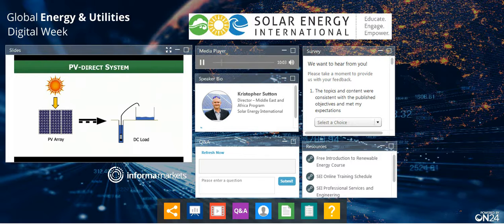So we have to understand the limitations of this are daytime only, but it's also very simple, and it saves a lot of money if we don't have to have batteries and a lot more maintenance, troubleshooting, costs, things like that. Now, there are actually a number of specific inverters on the market today that can do PV direct water pumping to an AC three-phase pump motor as well.